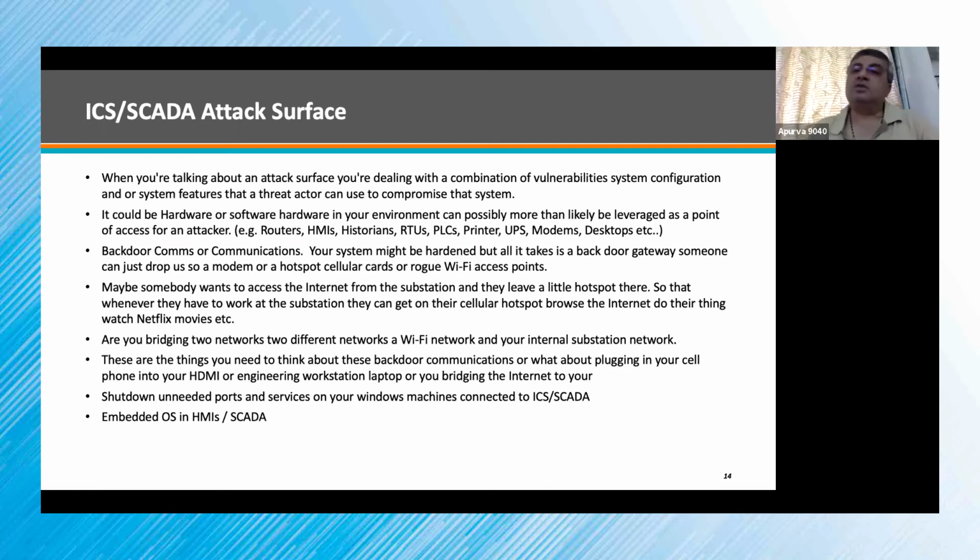You have to shut down all the unneeded ports. What you do for your IT systems, you have to do similar things on your OT side also. When you are implementing your SCADA, look at which ports are not required and shut down those ports, shut down those services, because those are the attack surfaces.